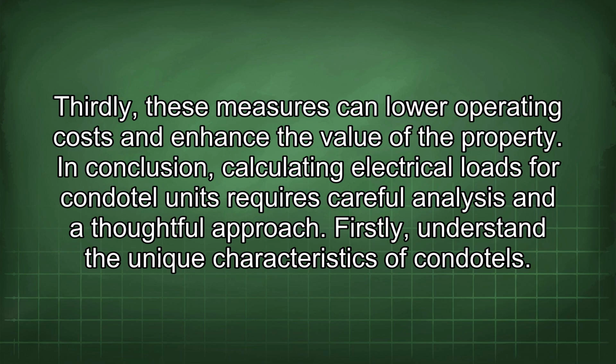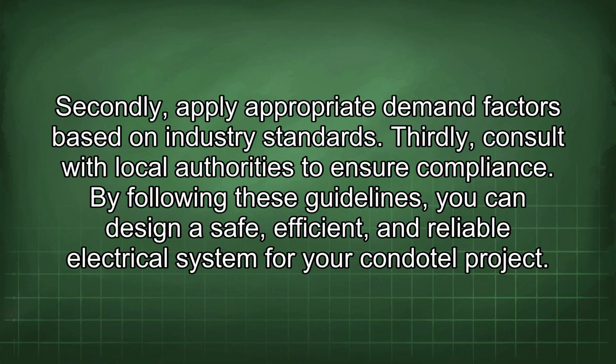In conclusion, calculating electrical loads for Condotel units requires careful analysis and a thoughtful approach. Firstly, understand the unique characteristics of Condotels. Secondly, apply appropriate demand factors based on industry standards. Thirdly, consult with local authorities to ensure compliance. By following these guidelines, you can design a safe, efficient, and reliable electrical system for your Condotel project.